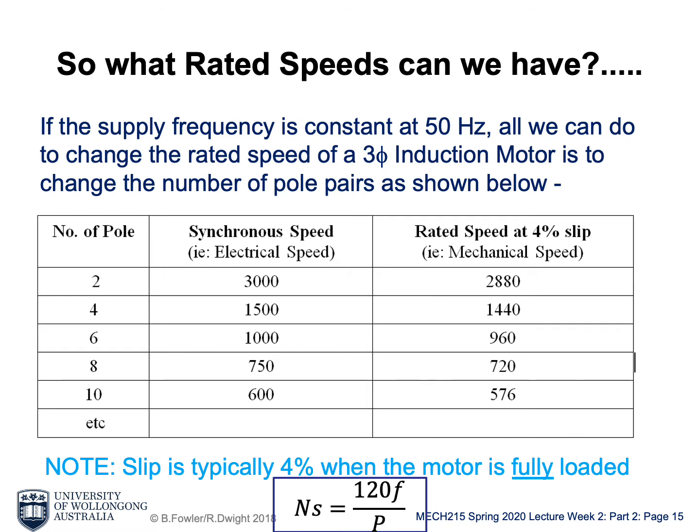This means based on the gear ratio, you can't get the exact motor speed. You should pick a motor speed that's very close, then go back and recalculate the gear ratio based on the nominal rated speed of the motor output.